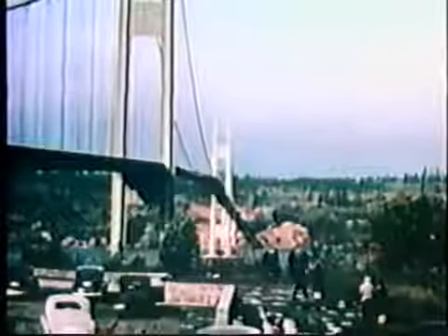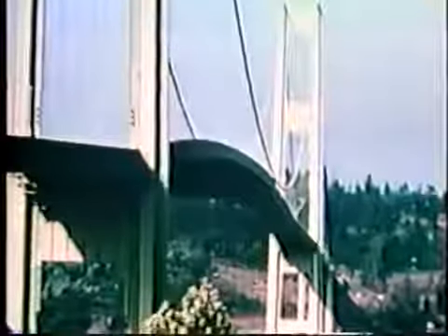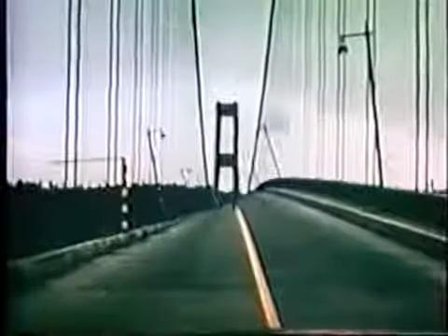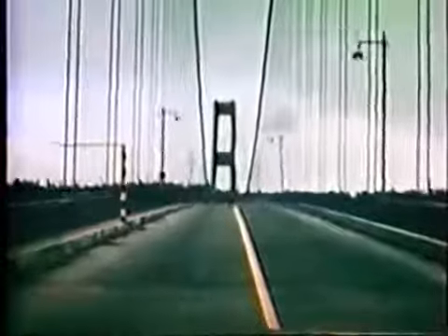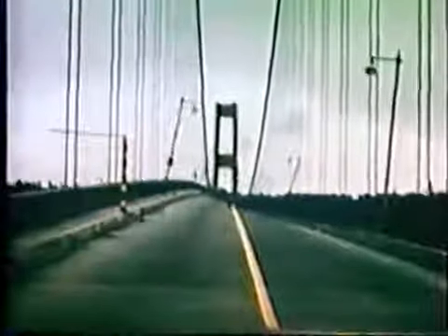The fourth movie shows the dynamic response and collapse of the Tacoma Narrows Bridge in 1940. The Tacoma Narrows Bridge collapsed on November 7, 1940, about 4 months after its opening, in winds of 40 to 45 miles per hour. Here you see the dynamic motions of the bridge prior to its collapse. A side view, and now a view along its center line. Notice the high torsional vibrations of the bridge. The bridge went through large dynamic motions for hours until its collapse. We only show a very small segment of that time. And here you see how the bridge collapsed.